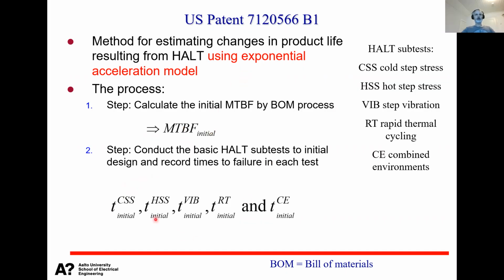So now these values, what you have is the initial value, how much your product withstands these cold temperatures. If you start from room temperature, then with 10 degree steps, you go downwards and you keep there every 10 minutes. So you have +10, 0, -10, -20, -30, -40.